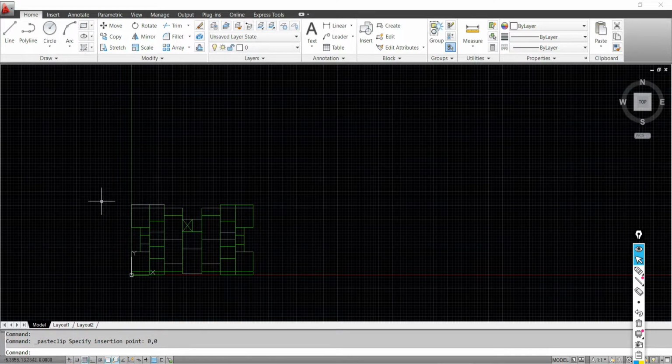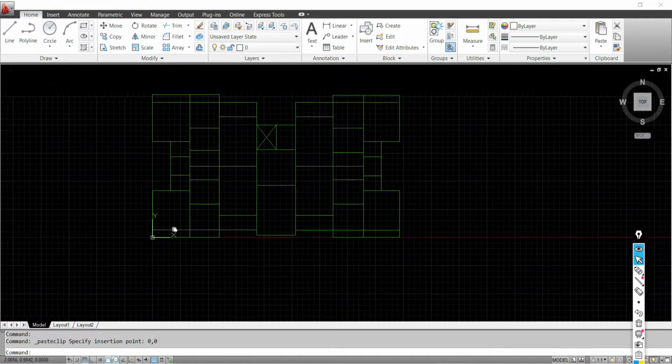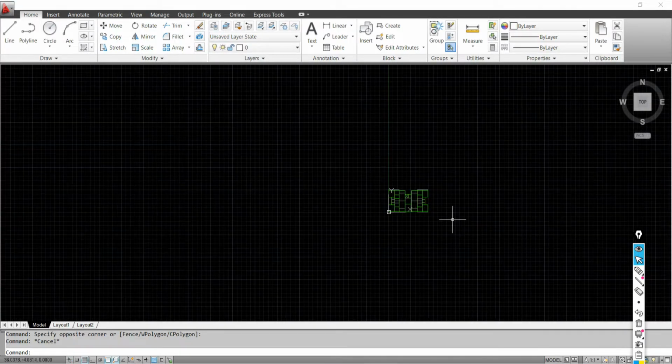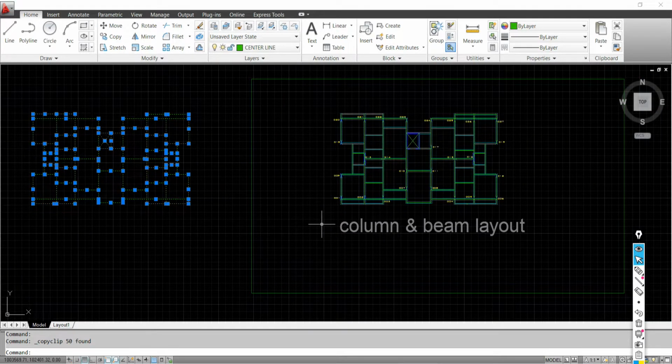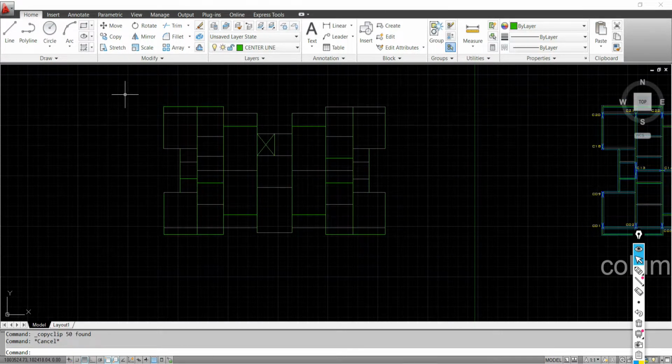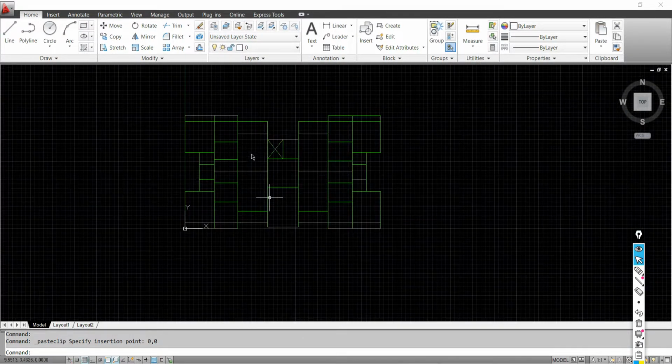So this drawing is going to be shifted, or positioned, with respect to its origin, means in reference to the origin. Once again, sir, why we are doing this, you will understand later. First step: open your drawing which has the structural framing plan, prepare the center line plan, and after that we will have the center line plan. That center line plan you have to take outside, and you have to create a new file. There you have to save this file.